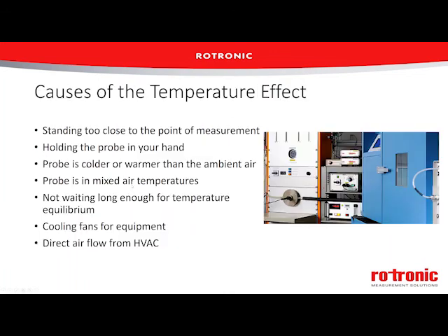So there are a lot of causes of the temperature effect. It can be as simple as standing too close to your measurement point. Not only when we breathe do we put out a lot of water vapor, but our body temperatures can increase the local temperature. Same for holding a probe in your hand. If you're holding too close to the sensor, you're going to heat that sensor up. And if that sensor is warmer, then it's going to report a lower relative humidity.